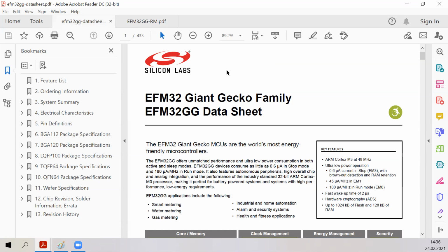And now I will try to explain to you why everybody isn't using microcontrollers from, for example, Arduino family, or why isn't everybody just using some high level programming language, or why isn't everybody just programming in Python? Why do we need to program in this low level C programming language? And the reason is that the lower language we use, the more precise control we have over microcontrollers' energy consumption.